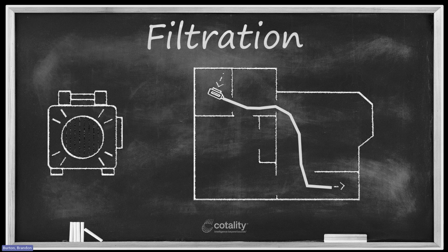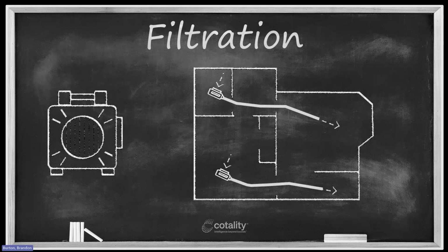This is exactly how a forced air system is engineered, right? We have an intake at one part of the structure and then exhausts all over the structure to create good circulation of the air throughout the space. So engineer your supplies and returns, okay? Even better yet, if you need multiple air filtration devices, depending on the size of the space, then do it multiple times, right? With intakes in different areas and exhausts in different areas, okay?